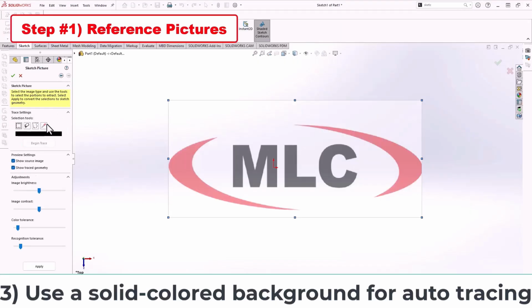The last suggestion is try to use a colored background if possible. I didn't use it for this project, but if you have a solid background, you can take advantage of some auto tracing in SOLIDWORKS instead of sketching your own profiles. It works really well for something like a logo, for example.